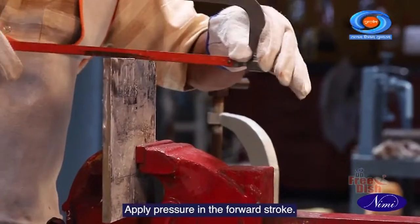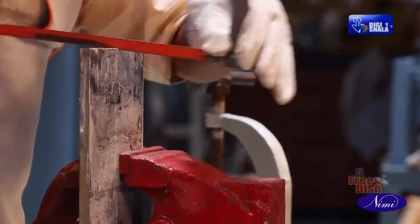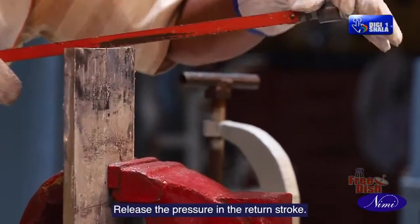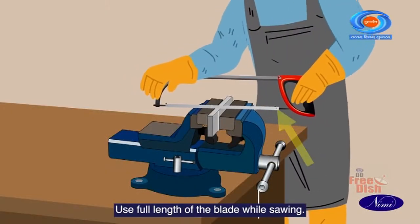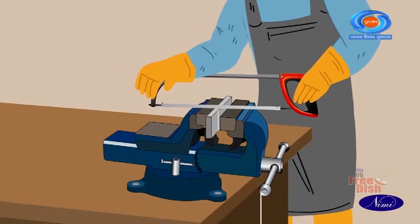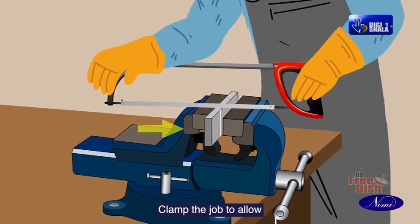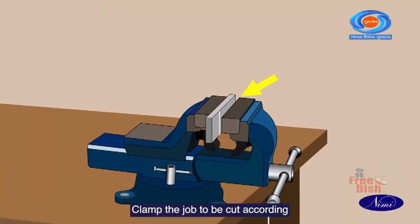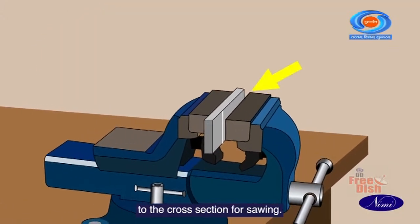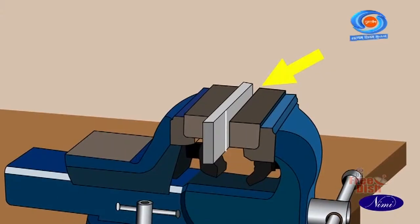Apply pressure in the forward stroke. Release the pressure in the return stroke. Use full length of the blade while sawing. Clamp the job to allow sawing towards the overhanging end. Clamp the job to be cut according to the cross section for sawing.